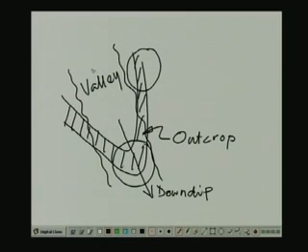So the valley could slope in this direction, or this could be the valley slope, or the valley slope could be the other way around. Irrespective of the direction in which the valley slopes, the down dip direction is going to be pointing towards the sharp corner of the V if you have got a dipping layer crossing a particular valley.